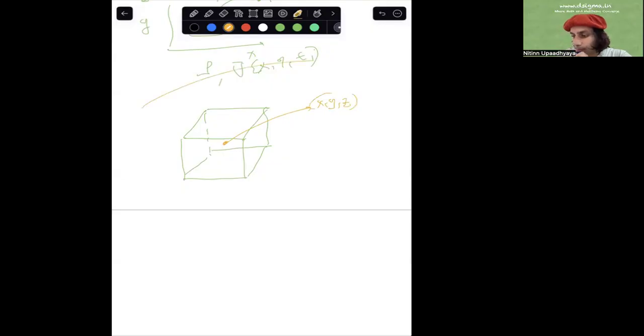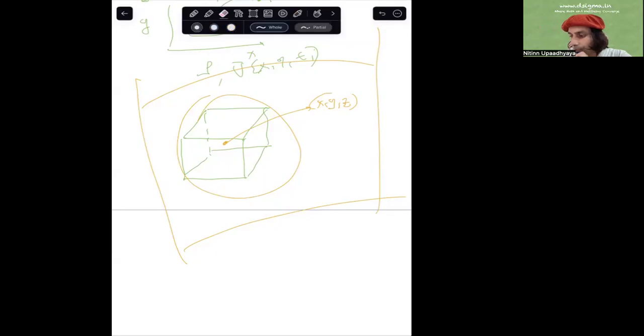And this is some fluid that's there. Maybe it's in a static condition. Maybe you're holding it in a tank. And I'm just picking out one element, one differential volume in that finite volume. That's kind of the idea we have in mind here, right? So let's say this differential element is located at the point x, y, z. So time is not a variable for us because we're just assuming static conditions, no flow.